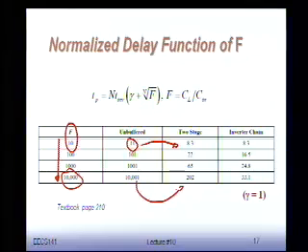But actually it turns out that if you have the total optimal number, which in this case uses a factor of 4 for every stage, so you can figure out exactly how many stages you need, we see you can go down to 33. Absolute minimum delay. You cannot go any faster than that. The only way to do it would basically be to have a better technology. Right? This is for this technology. That's the best thing I can do, which is 33.1 times T invert. Okay?